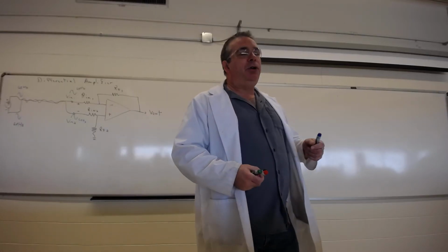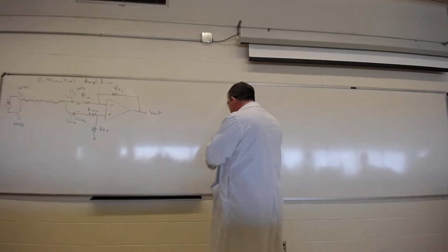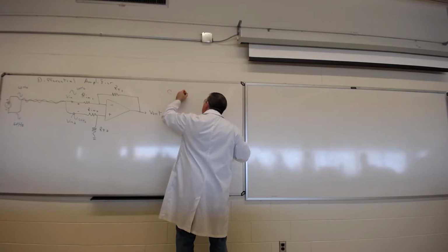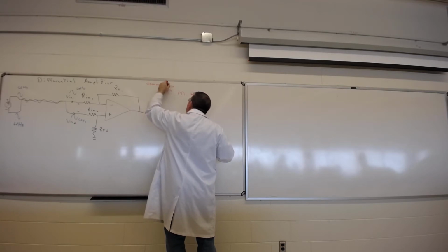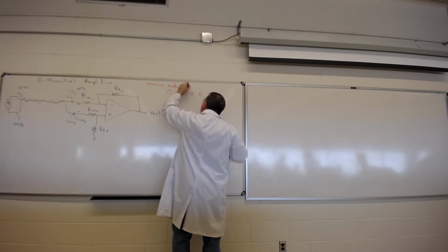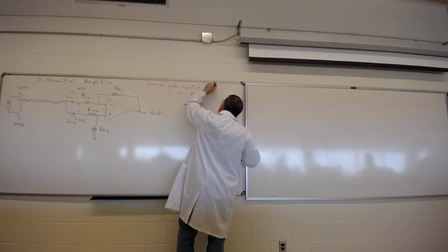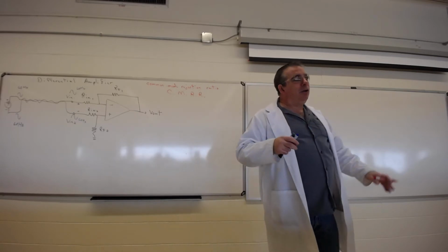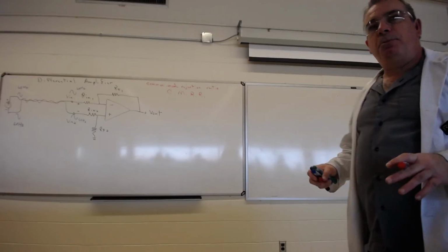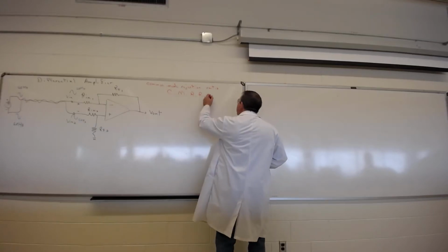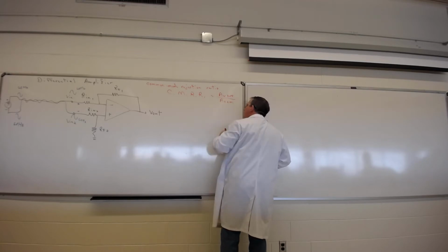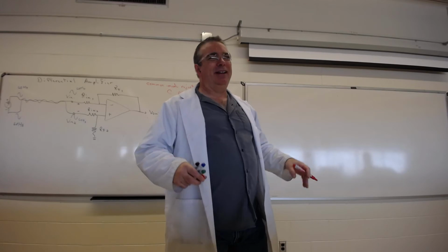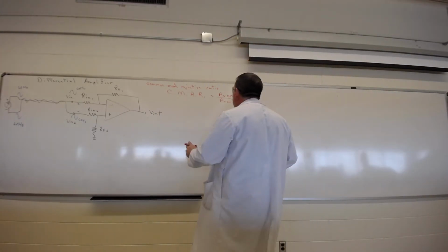So there's a specification, when you're looking at a spec sheet from an op amp, there's a particular specification called the common mode rejection ratio, CMRR. I'll write that down. That's common mode rejection ratio. A little number. Now I could go through a whole discussion on how they come up with that. It's usually measured as voltage gain differential, so AV diff over AV common. There's a method to measuring all that. It's not something for electricians, it's not terribly important. You should just know what the number means.